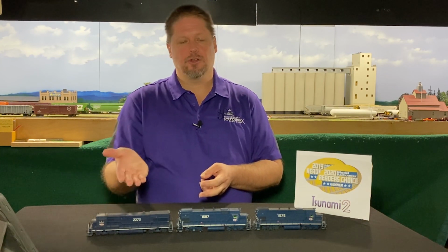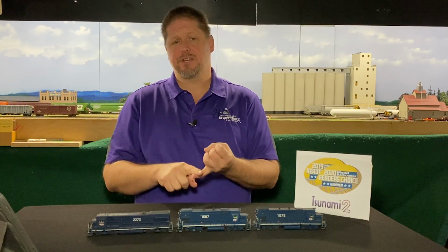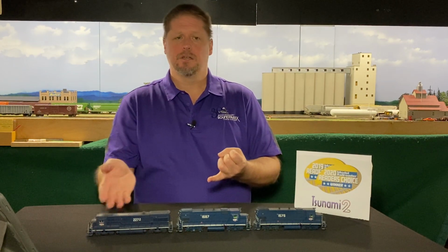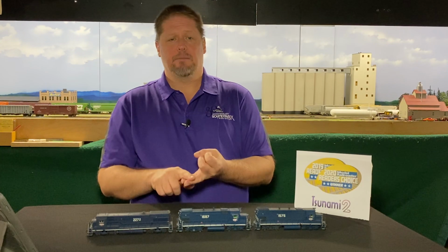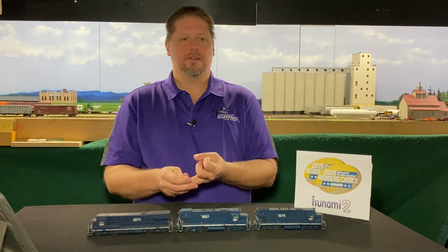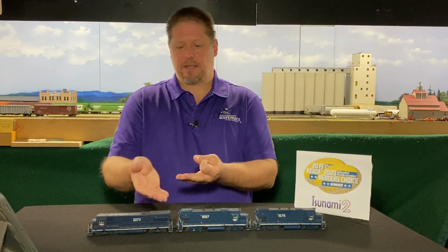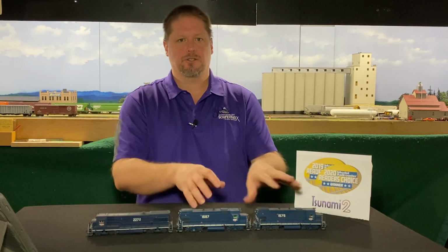Now the last one here, Locomotive 2272, says, hey, I'm part of consist 20, but I'm supposed to move reverse, speed step 10. So it moves in reverse, speed step 10. Its F0 command comes through. Am I supposed to respond? Nope, ignores that command. Am I supposed to respond to the F1 command for the bell? Nope, it ignores it. Am I supposed to respond to dynamic brakes? Again, let's assume it has dynamic brakes. Yes, it does, and it responds accordingly.